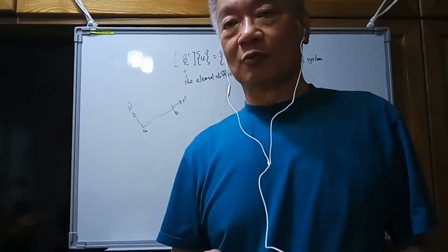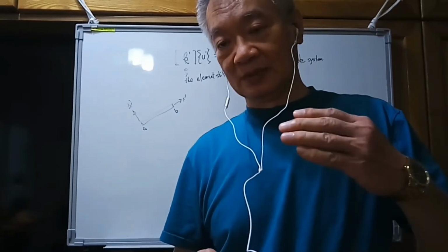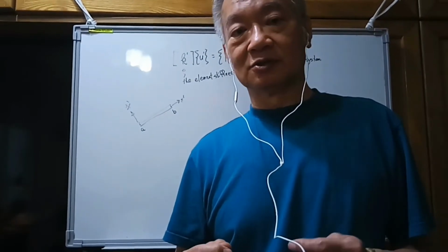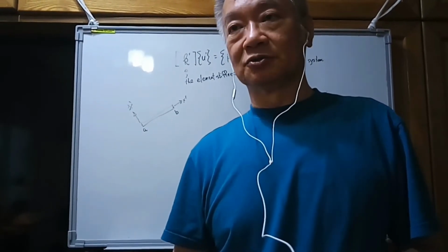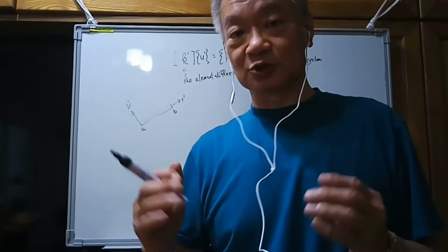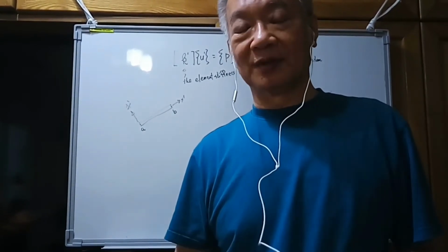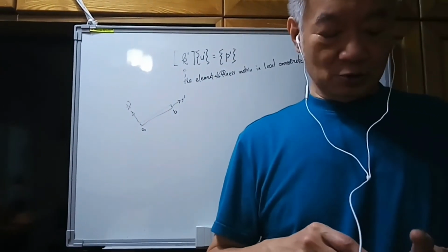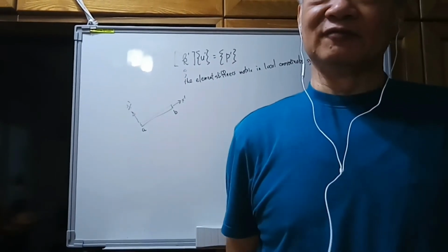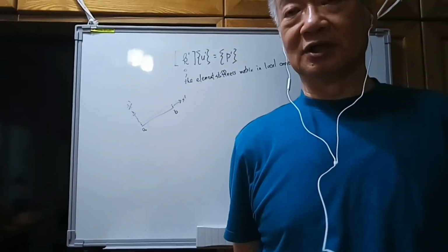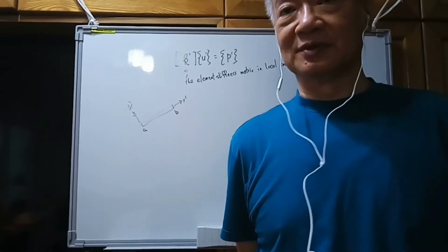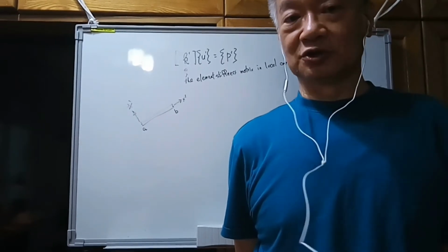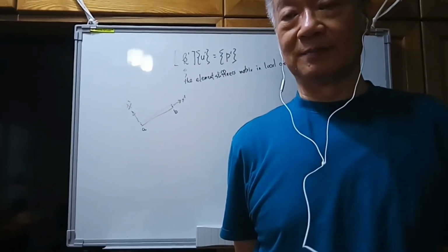Then if we consider the y prime direction, which is the vertical displacement of this element, the vertical displacements are usually related to the flexural deformation and the shear deformation. When we derive the stiffness matrix related to the vertical displacement, we need to consider the flexural deformation, which is also called the bending deformation.